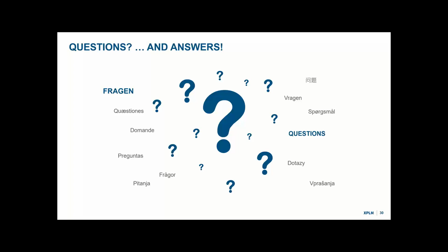Perfect. And then, is it fairly easy to migrate existing Altium libraries? Yeah, so Altium libraries, there's a whole bunch of different flavors. The most basic is what we call the schematic lib, a bunch of files sitting in a folder. The next step up is the DB lib, where you've got a basic database library. And that's still free, right? It's just a matter of converting your schematic lib to a DB lib. But the DB lib level is really the level you should be at to have a good connection to PLM, right? We would sync up that database library to your Windchill parts. Got it.